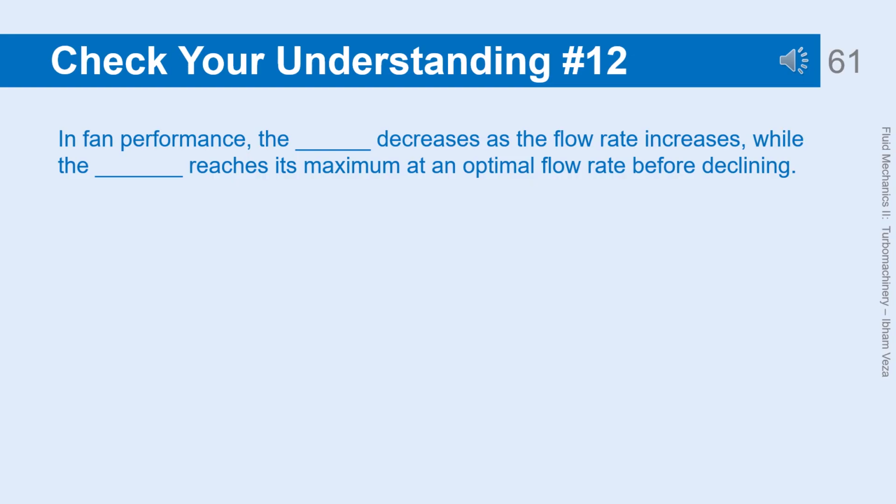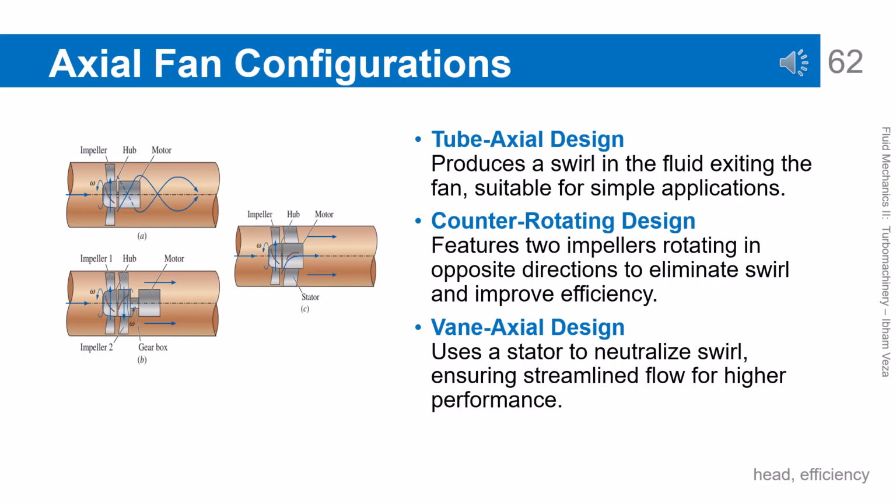In fan performance, the head decreases as the flow rate increases, while the efficiency reaches its maximum at an optimal flow rate before declining. Axial fan configurations.